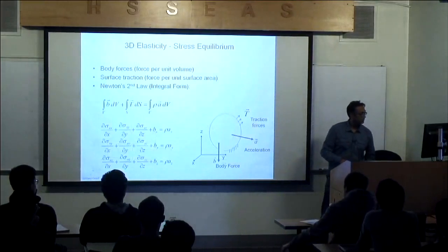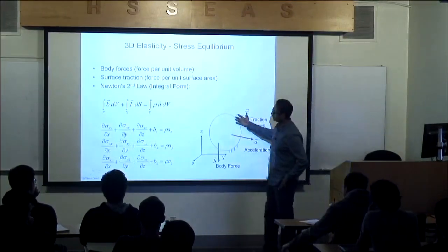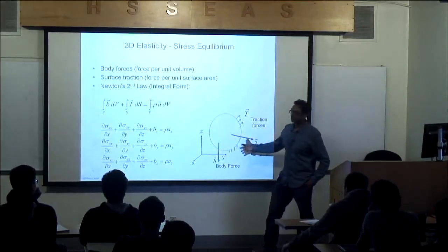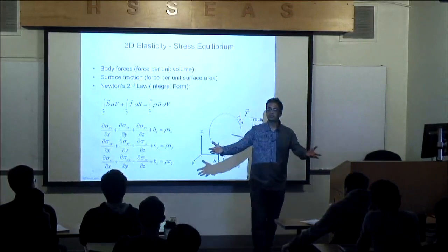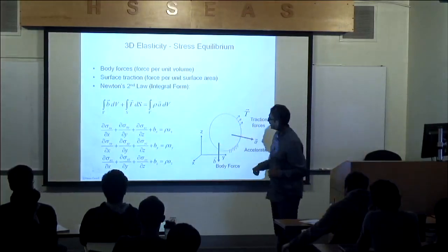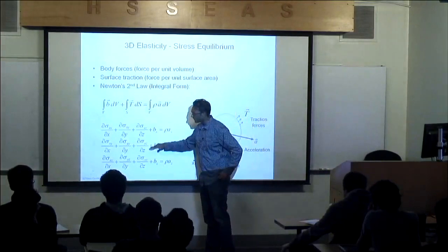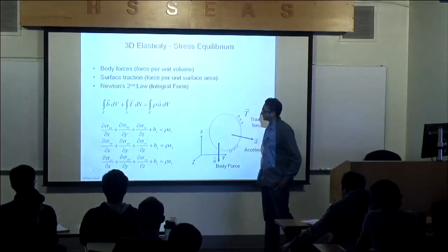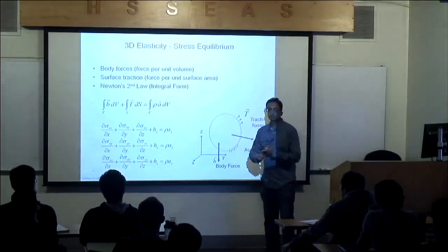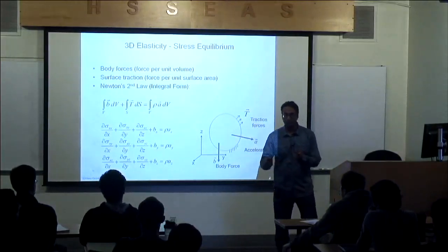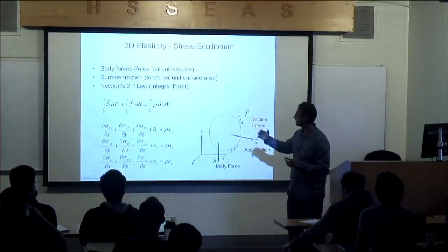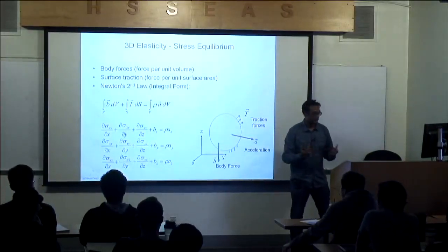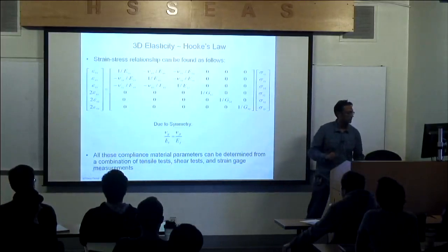We also covered that in a problem, I apply traction forces, body forces, acceleration, and why not keep the acceleration forces? You know how to tackle transient problems now, so we'll just keep that there. And we have 3 equilibrium equations. They're dynamic equilibrium equations. And from these 3 equations, given the stresses, the strains, the displacements, and the relationships between stress and strain, perhaps we can determine the solution to the problem. And you can see it's highly coupled. You cannot really do it by hand very quickly.